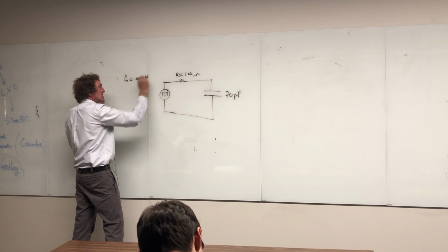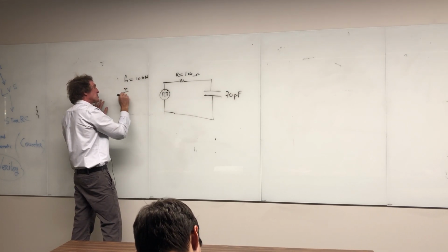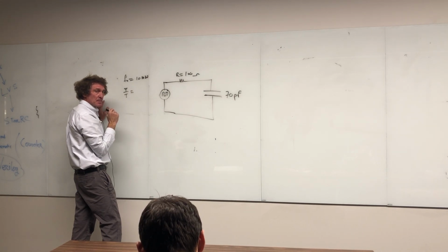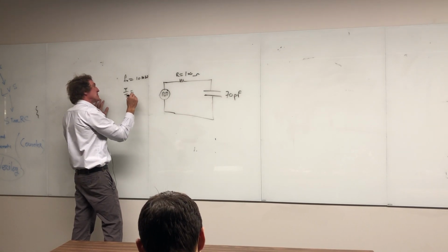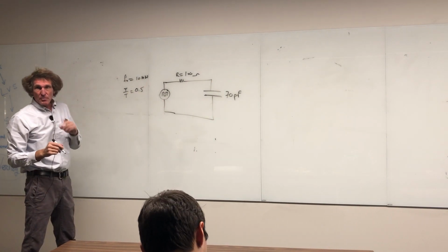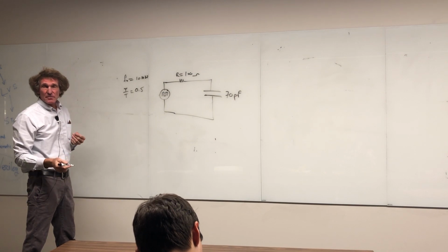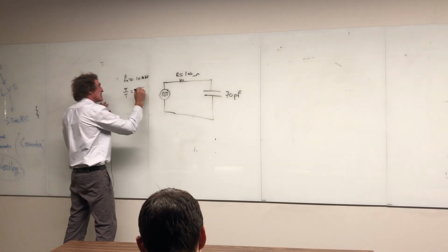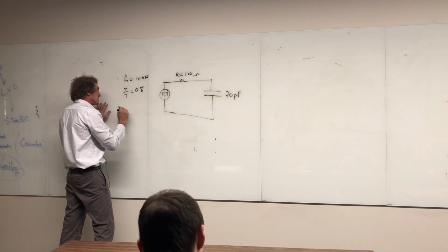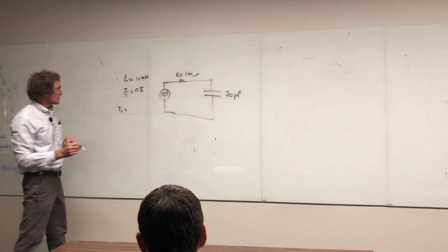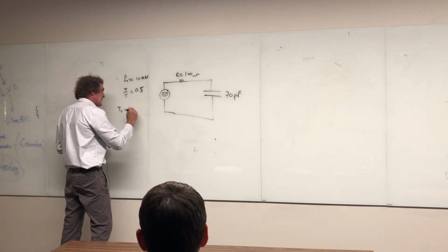Now just hang on. And then they give you tau over T, or the duty cycle, which is 50%. The duty cycle's 50%. So that means this is 0.5, all right? 0.5 is 50% if we talk in fractions, right? And it would be 1/2. Then after that, they give you one other thing, the t rise. Now this is the important one, t rise. That'll be 20 nanoseconds. 20 nanoseconds.